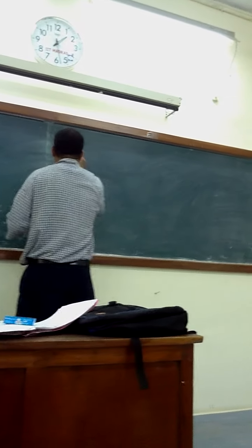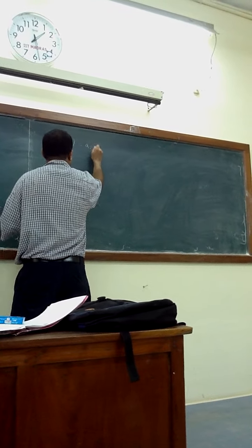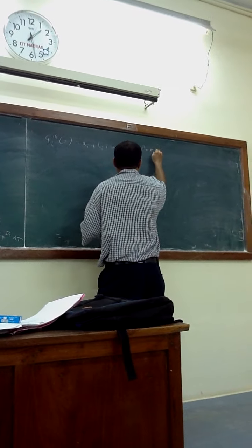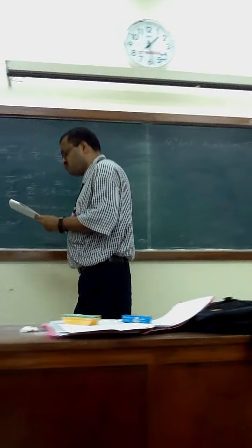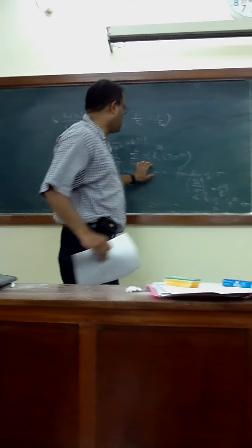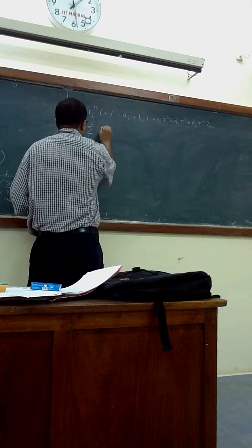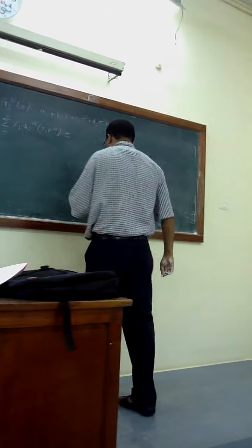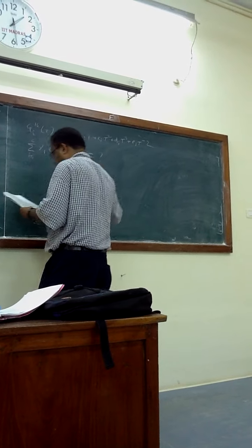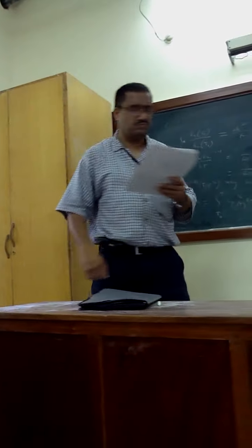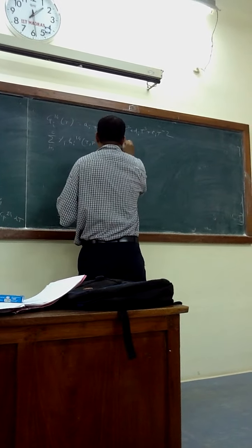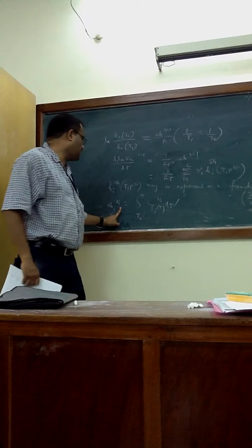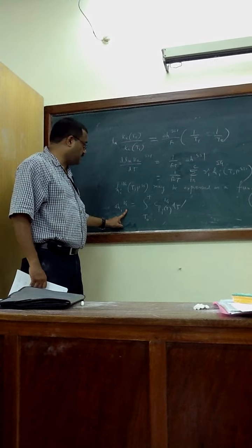Okay, so let me write the form of Cp^IG. Cp^IG(T) is A_i plus B_i T plus C_i T square plus D_i T cube plus E_i T to the power minus 2, for component i. So, summation i equals 1 to C of gamma_i H_i^IG at T, P standard state, we have to calculate. And you can see from here delta H^IG means H^IG at T minus H^IG at T0, right?